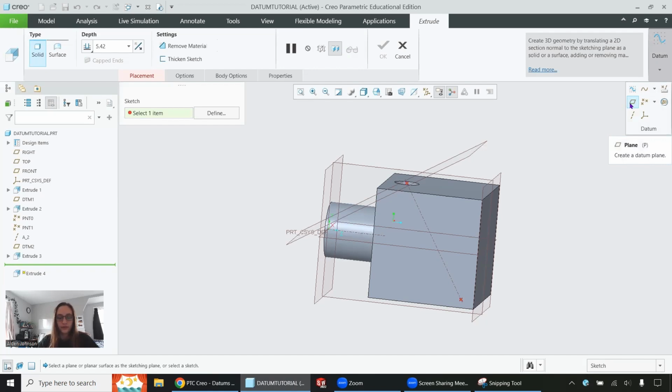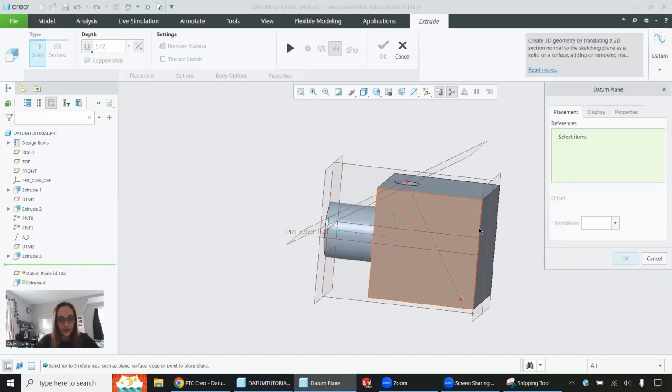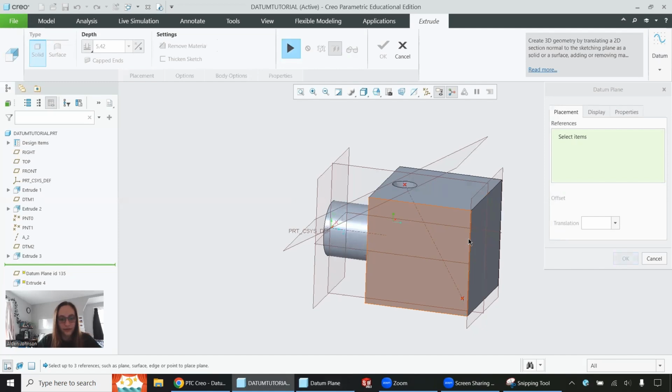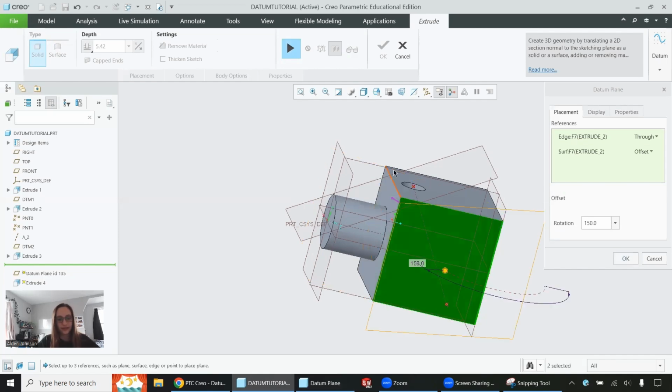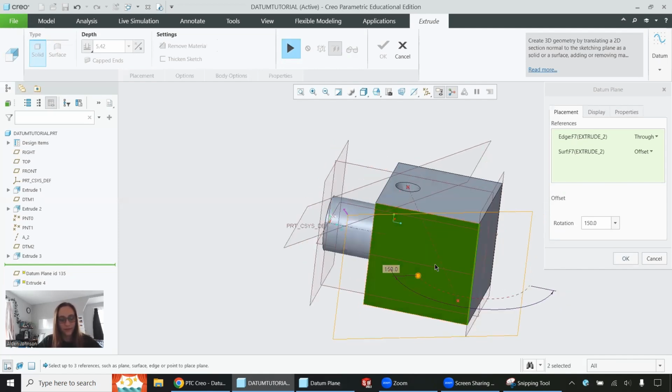I want to create a plane. So one thing that I can do is I can reference this axis and holding my control key, select this plane. So it's basically making a copy of this plane that's being rotated about the selected axis. And I can change that to be 45 degrees, and you can see it moved this way. 60 degrees, whatever I may choose.